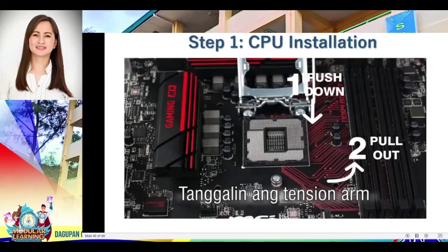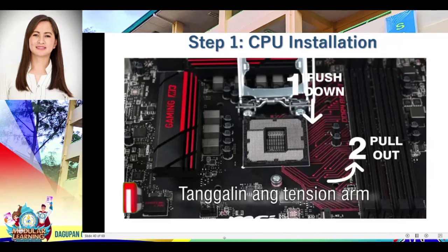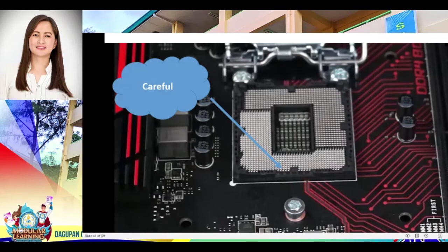Open the computer case by removing the side panels. Find the screws that hold the side panel in place and remove them. The panel is removed by first sliding it back, then lifting it away from the case. Case may have sharp edges. Handle with care to avoid injury.